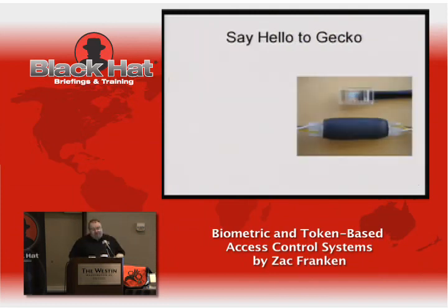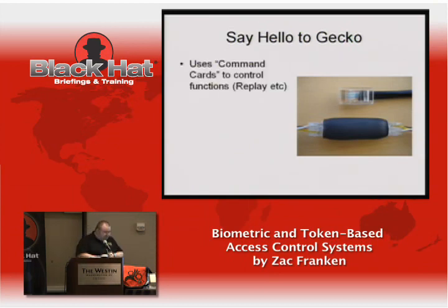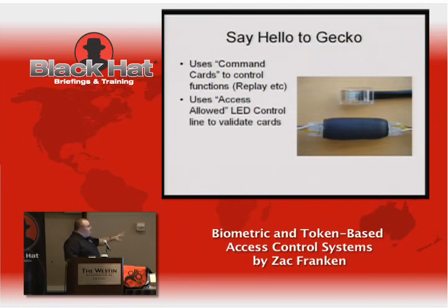So what you've been looking at is a little device called Gecko. It uses command cards. It's got its own little set of cards to control its functions, like replaying. It uses the access allowed LED to validate the card. So when it sees a card ID go past, it looks at the access allowed LED and says, oh, did you just go high? If you did, I'll mark you as a valid card.